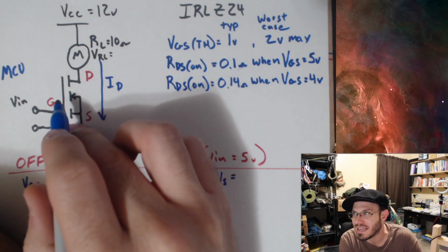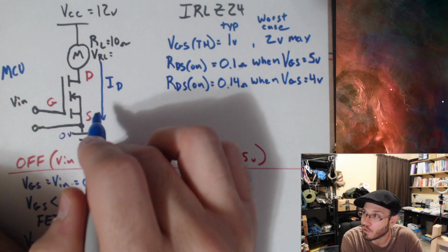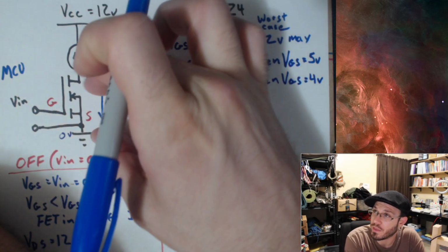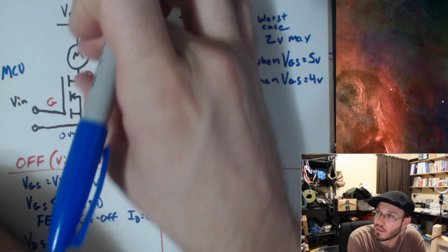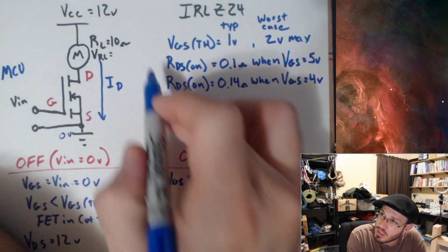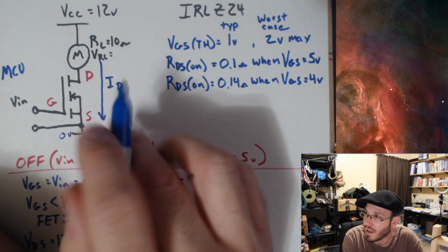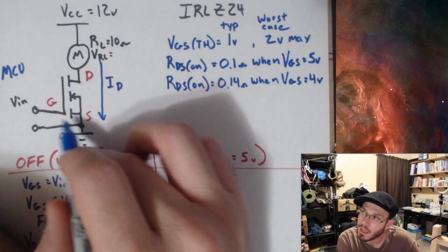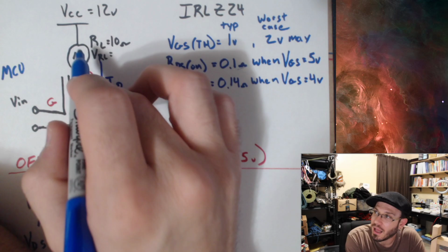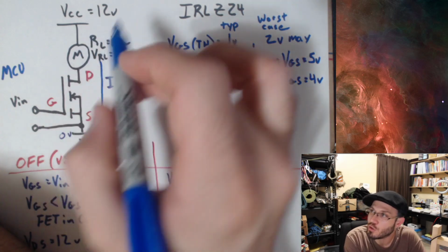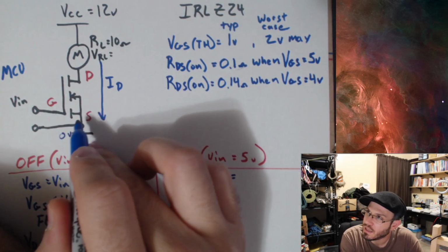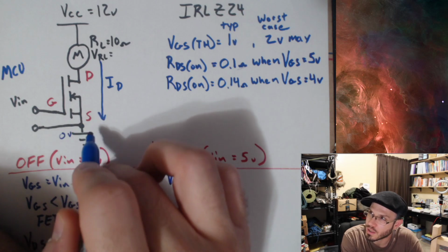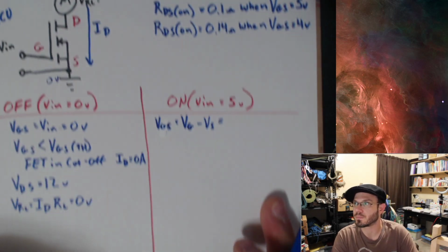Okay, I'll do an example of that later if you're a little confused by what I just said with the MOSFET being above the motor and the motor being below. Just know that an N-channel MOSFET, for right now, must be below the load that you intend to put current through, specifically because we want the source connected to ground.